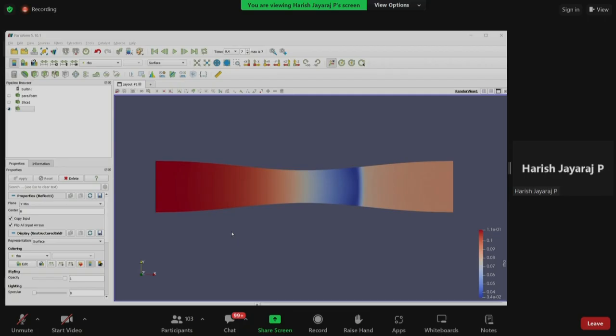Okay. So either your mesh is not small enough, if it is a transient case, or your time step is not small enough. A floating point exception error is the case where the equation is hit by a divide by zero. So it continuously generates decimals and we could not get a finite value. That is why we are getting the floating point exception error. If you look at the residuals, they will just blow up instead of going down. But if you want to solve it, you can try to reduce the mesh size or reduce the time step. You can check with the stability criteria formula.